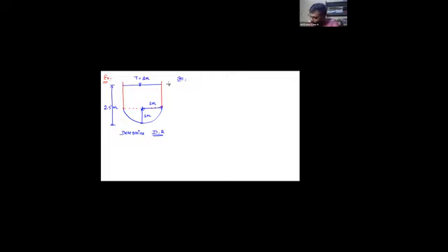And what about the remaining value? This value is going to be 1.5 meters. So now, please tell me the details over here. First, what is the top width? The top width is going to be 2 meters. And what is the wetted perimeter? The wetted perimeter here is a side 1.5, and this is 1.5, and then the perimeter of the semicircle.